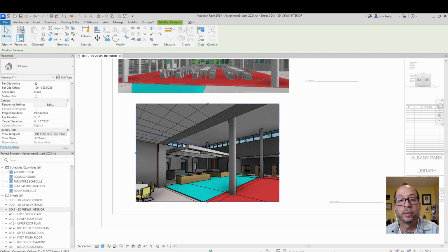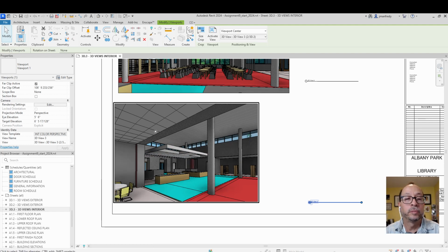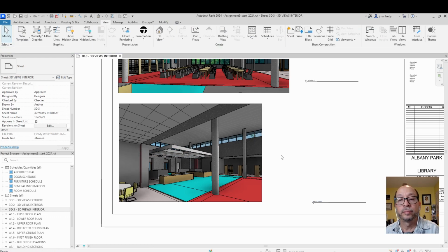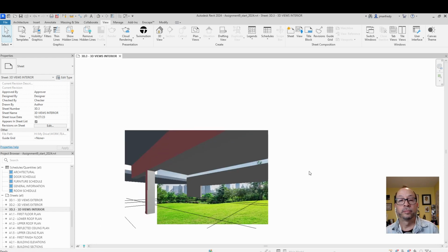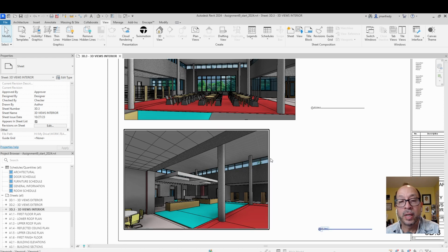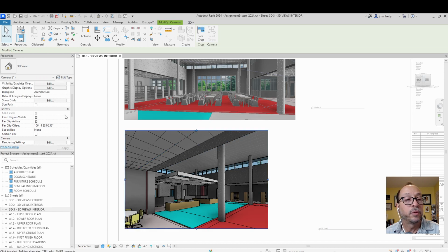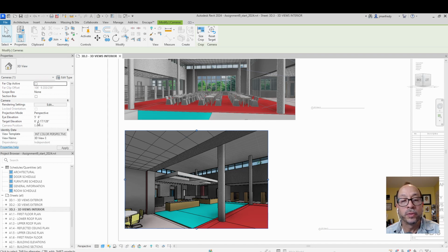Less floor and more ceiling is what you're after. Does that look okay? And then check the camera. Looks like maybe the camera's too low. Let's see what's going on with the camera. Click on the camera. Camera is the box. Here it says, again, spark clip is always turned off. Don't forget. And here it says the camera is 5'6" looking up at 6'5". Something's off. So let's make it 5 feet looking up at 5 feet.